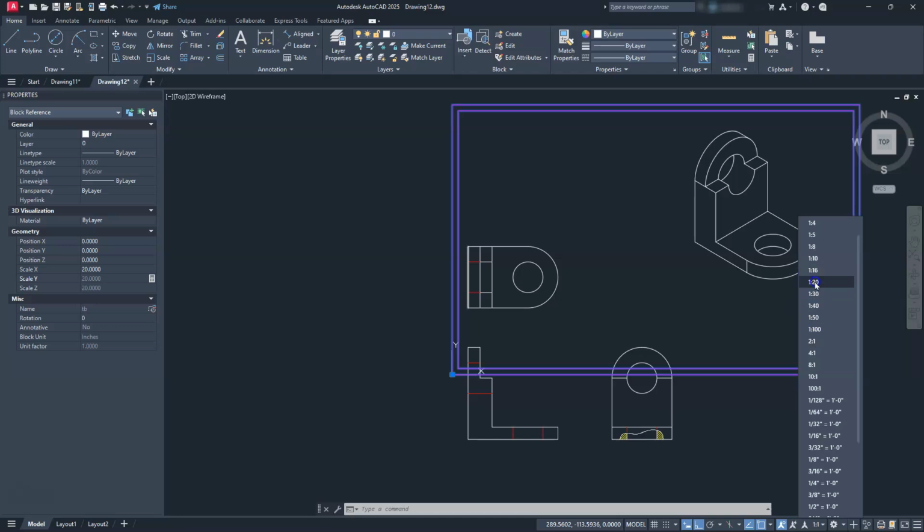And if I did set it equal to 20, then remember that the scale factor I'm going to put inside of my drawing will be not to scale, right? Because I am not mixing my metric with my imperial units. Now, if it is 24, then by all means, go ahead and put your 1/2 equals a foot. So that's another one of those rules. You do not want to really mix these two, one or the other.